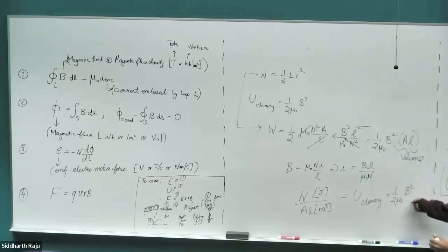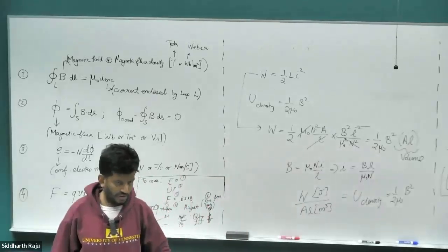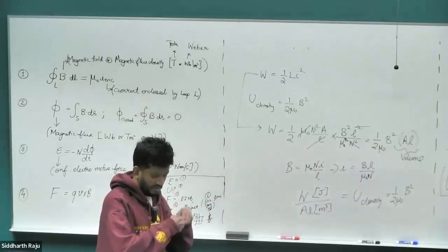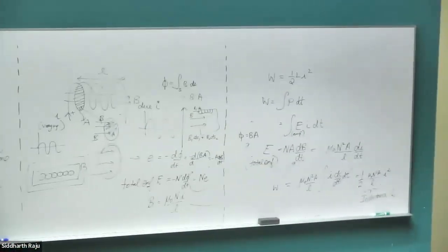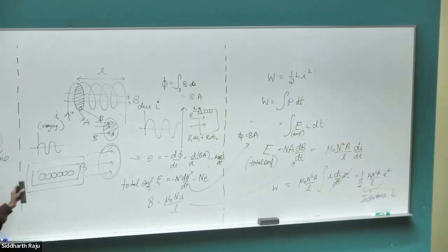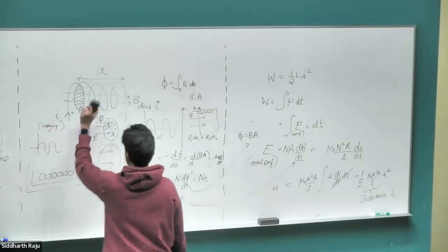So this was the equation we used when we compared the energy density of magnetic field compared to that of an electric field, right? There was the one final equation that we hadn't derived, but we assumed. So with that, we are done. So this derivation, I did it for this very specific case of an inductor. This equation is not specific for the solenoid structure.